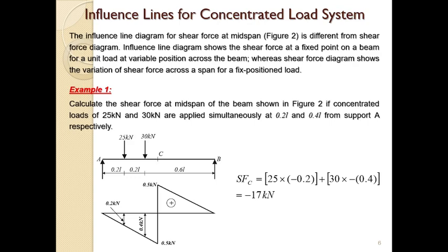That means you want to see how the shear force varies at a particular point as the load moves from one point to another. Whereas the shear force diagram shows the variation of shear force across a span for a fixed position load. So for shear force diagram, the load is fixed and you are plotting the variation of the shear force across the span of the beam where the load is applied.